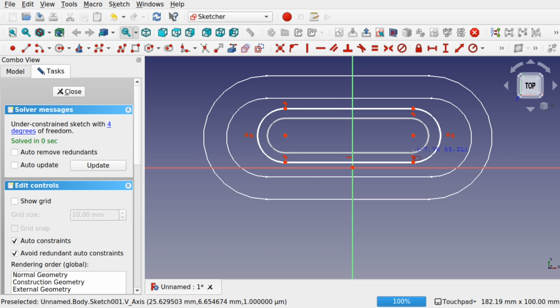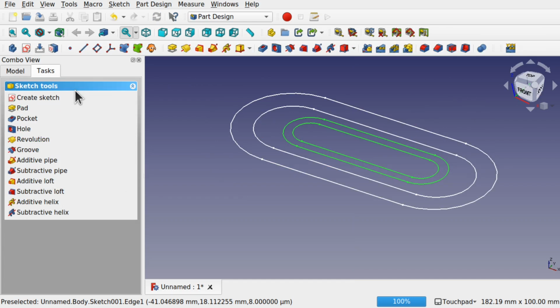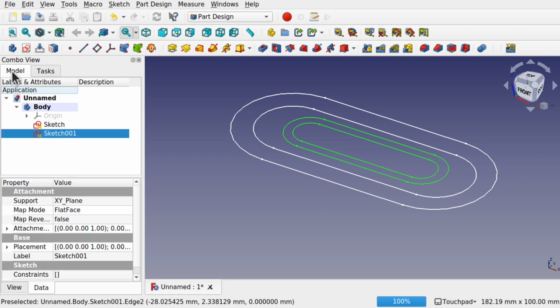So the problem I'm going to show you in a minute didn't actually occur to me until I made a copy mistake and actually went in there and changed some of the geometry. Let me continue with this and show you what I mean. So we've got our two profiles and we can loft between these, or if we had a third profile we can loft between that as well. So it's up to you how many profiles you have in there. We're going to keep to two for a second, and we're going to go through lofting these.